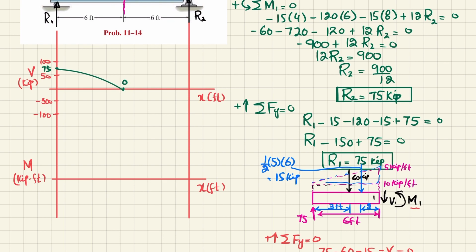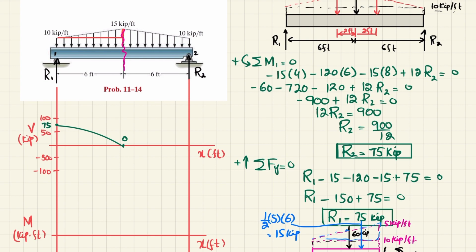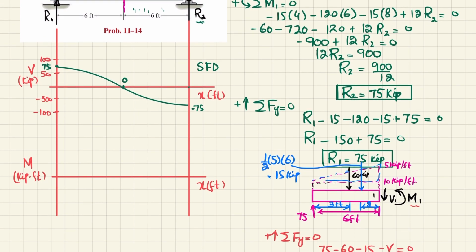Okay, now you can see the same thing here. The shear force will now increase and at this end you will get 75. So this line will continue over here. So it will be 75, minus 75. And at the end you have R2 is plus 75. So it will bring it to 0. So this is your shear force diagram. Now we'll move toward bending moment.